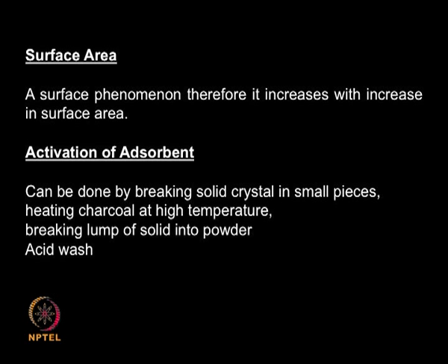Sometimes you heat the material, for example if there are any tarry deposits on charcoal or zeolite or even metal particles. When you heat it to high temperature, the tar gets burnt. So again the catalyst or the surface gets regenerated or reactivated. So using high temperature is one way of activating your adsorbent, and that is what is followed in many processes. When you are doing a hydrogenation, the nickel starts getting deactivated because of the deposition of oil and tarry material or waxy material. So again it is reactivated at higher temperature.